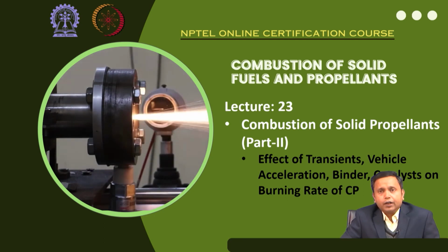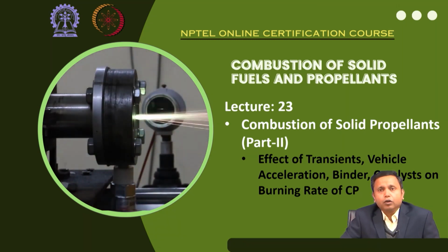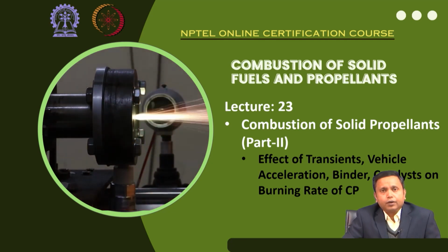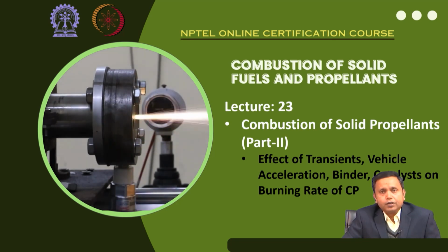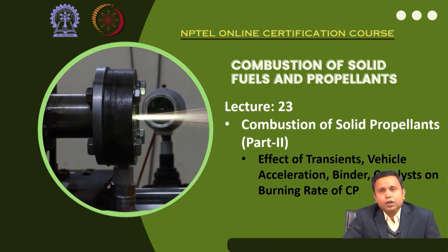Then we have said that there are various influencing parameters which we need to consider in order to understand the effect on the burn rate of composite propellant, and of solid propellant in general. Other than pressure and initial temperature, there are effects of transients, for example the effect of starts and stops, or the variation in chamber pressure, which is going to influence the burn rate. Vehicle accelerations and spinning: the motor is accelerating with a certain acceleration, due to which the burn rate of the propellant may also change.